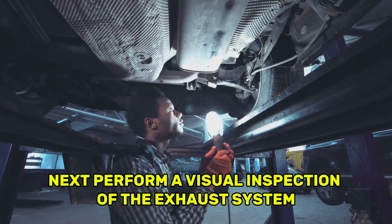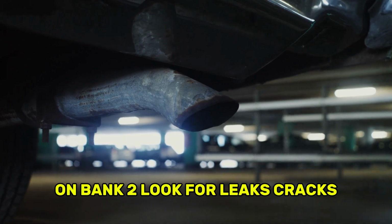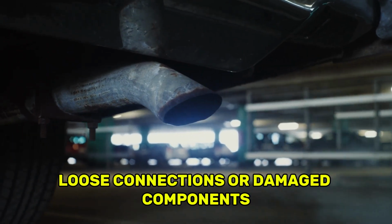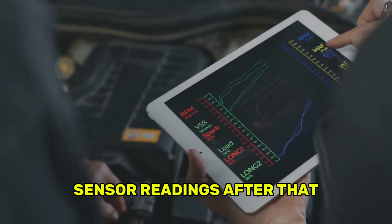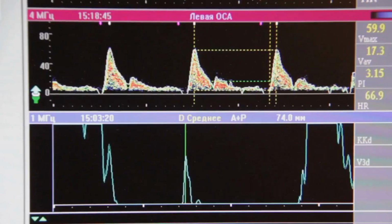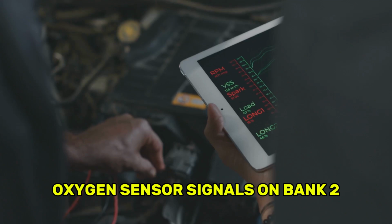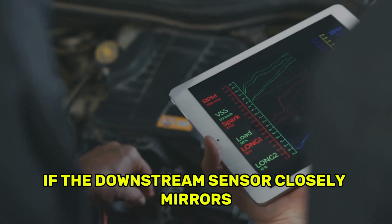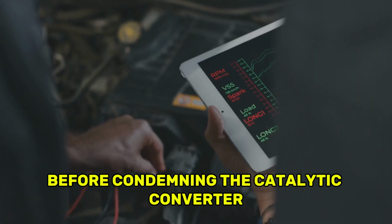Next, perform a visual inspection of the exhaust system on bank 2. Look for leaks, cracks, loose connections, or damaged components. Even minor exhaust leaks can significantly affect sensor readings. After that, use a scan tool to view live data. Compare the upstream and downstream oxygen sensor signals on bank 2. If the downstream sensor closely mirrors the upstream sensor, further testing is required before condemning the catalytic converter.